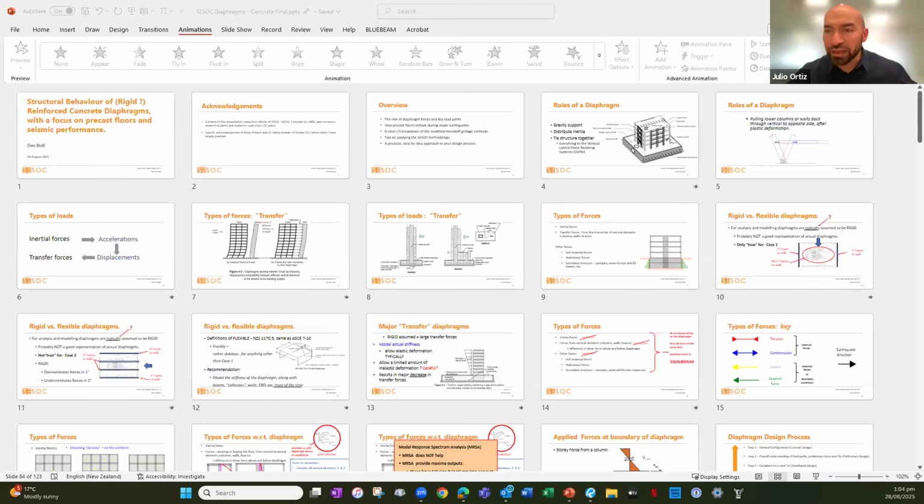Thank you. Can we rely on PT in post-tension slabs and the compressive stress in the slabs to reduce the tensile forces in the tie members? Yes, you can. Depending on the situation, if your stresses are keeping within the service load range of the PT floor, it's just an extra load in a PT problem.